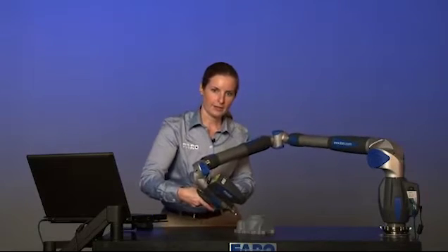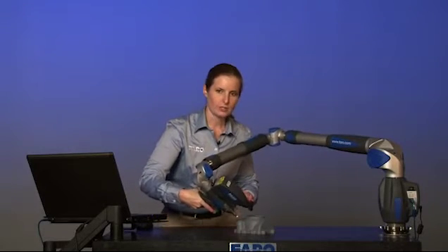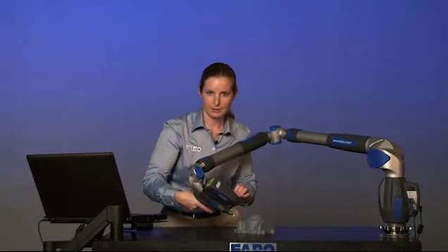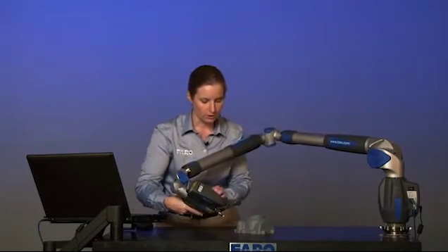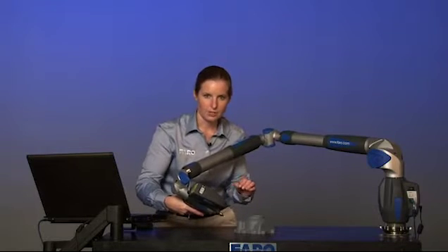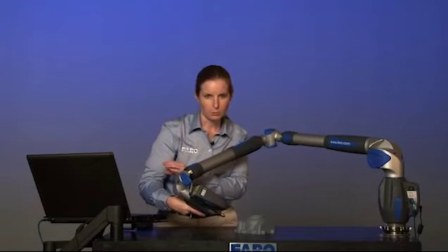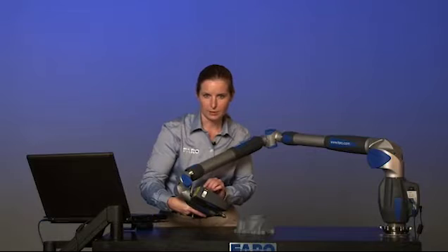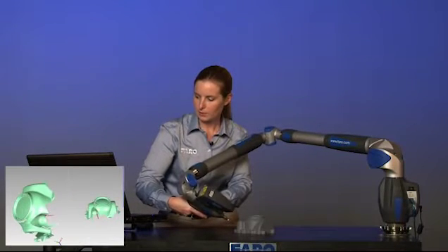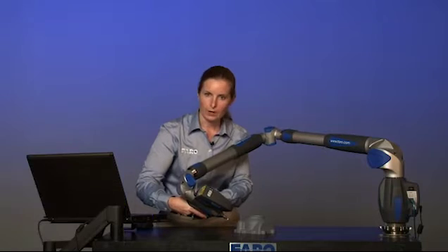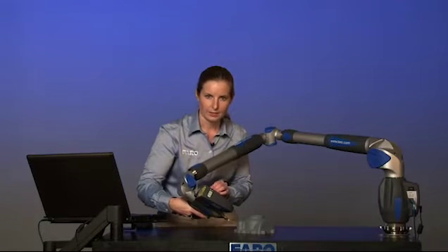The camera effect within the software allows you to see where you may be missing data within the scan. So adjust your scanner so that you can look at the part and tell whether or not the corresponding part on the CAD has gaps in the data or not. As you see right here, I'm missing some data on the part. So now I can concentrate in that area and gather more data.